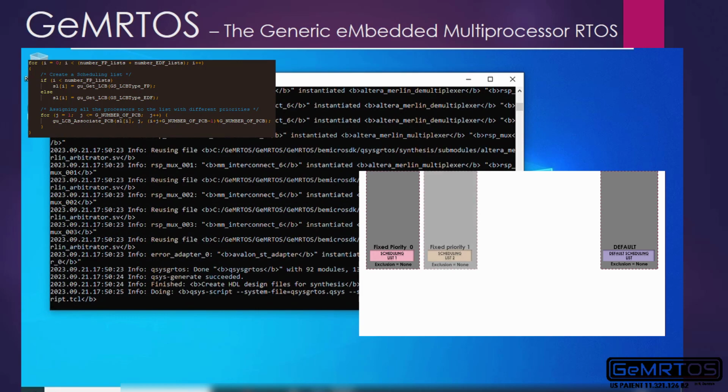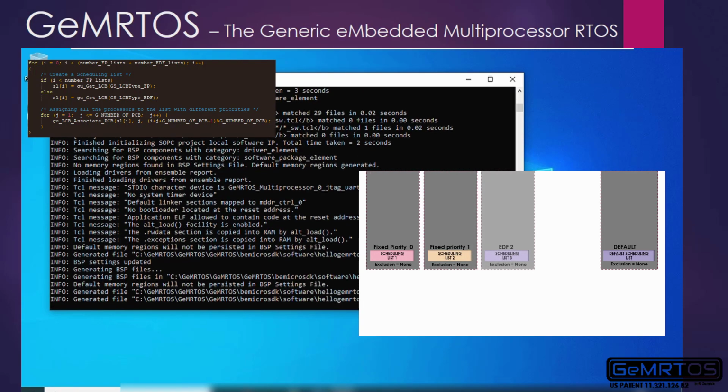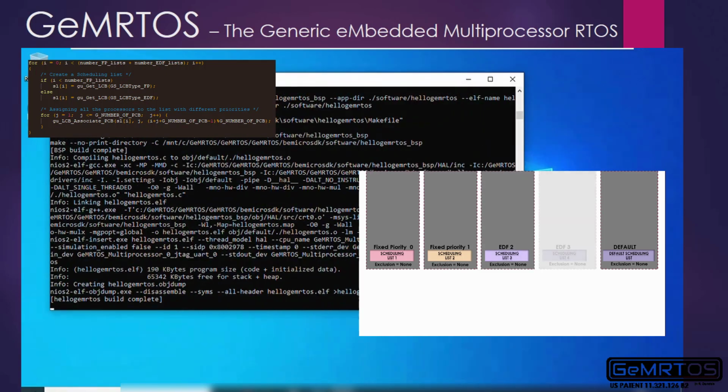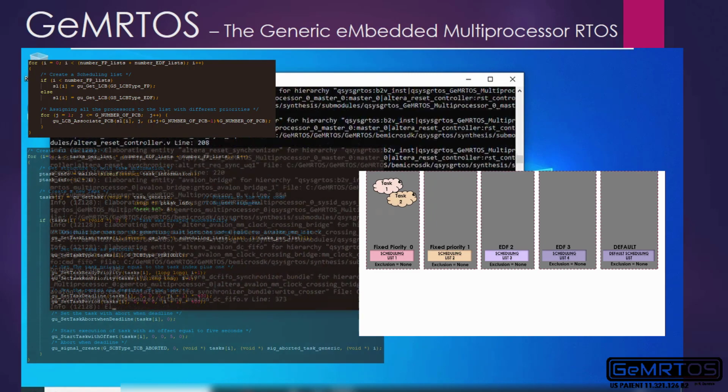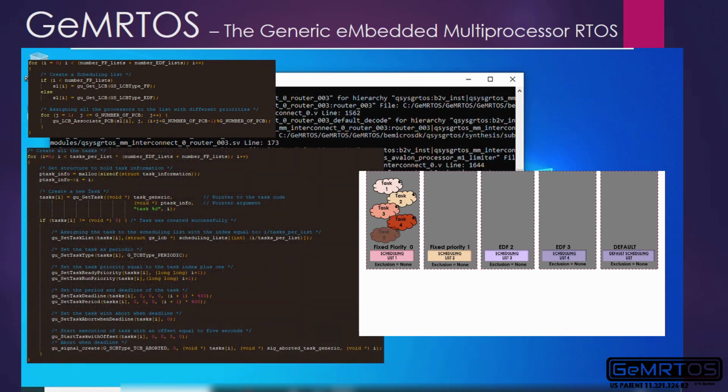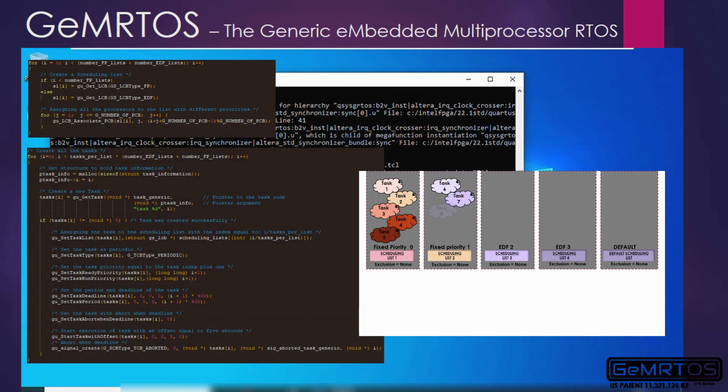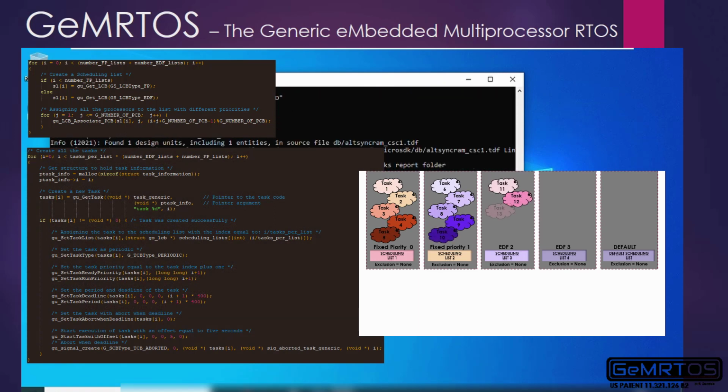Some of these scheduling lists employ a fixed priority scheduling discipline, while others utilize an earliest deadline first priority discipline. Within this template, a collection of real-time tasks is assigned to each scheduling list, and a producer-consumer scheme is established to serve the serial port included in the Platform Designer project.